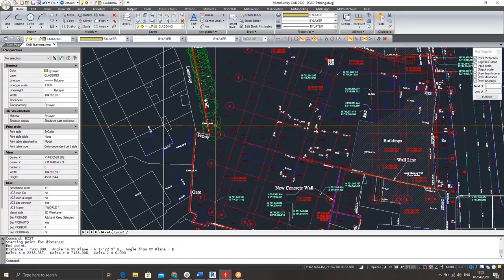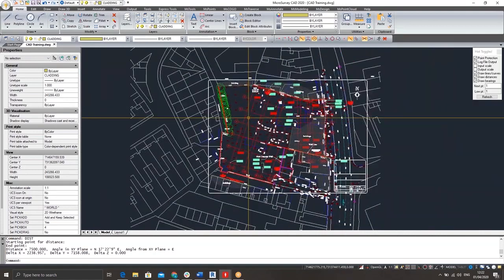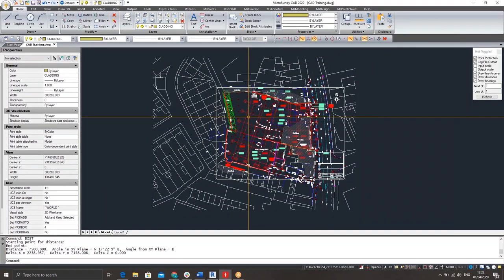So we need to understand our drawing before we import it into our field controller. It is not an issue with the drawing being millimeters or meters because we have in our import configurations within our field software the option to specify what unit the drawing is in. So it's a good first step. So what we can do then within the framework is we have an option: do we want to scale our drawing or do we not want to scale our drawing? So once we've identified, we can just make a note of it. We don't have to scale it. I'm going to scale it in this example for you guys just so I can show you how it is possible to do.